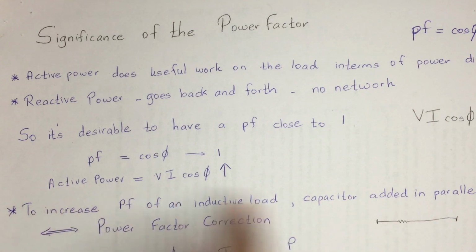But this process is known as power factor correction. You need to know this term, power factor correction, which simply means that to increase the power factor of an inductive load, you need to add the capacitor in parallel. So you need to know that.